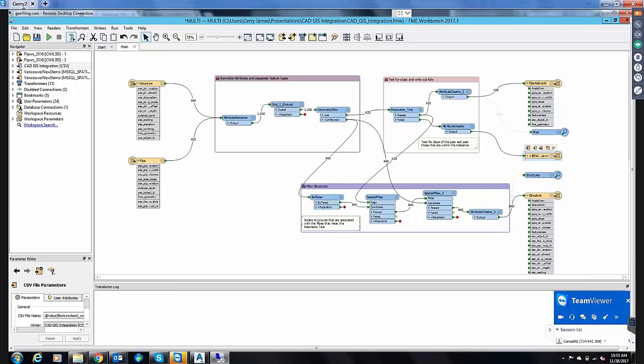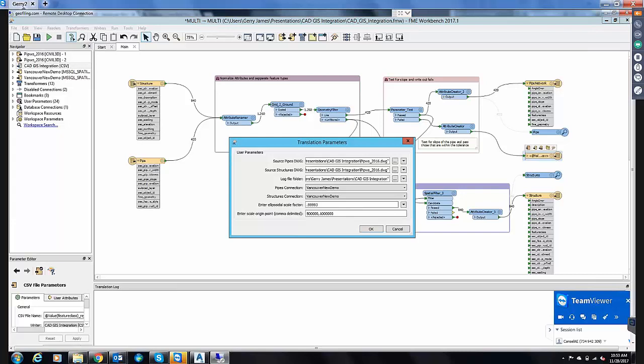Also, there are a number of ways to further automate this, so that you don't actually have to physically and manually run these workbenches in your environment. You can put these on a Windows Task Scheduler event, and it will run these workbenches on a timed event. There is also FME Server, which would allow you to drive these as on-demand events as well. Anyways, I'm going to quickly show you how this works. In the manual way, we just run the workbench.